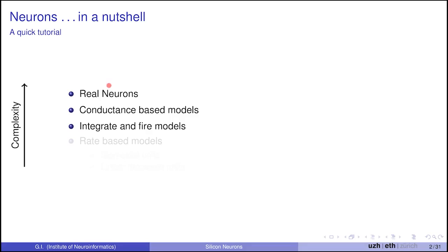Now, why would someone want to reduce the complexity of a neuron if you want to stay close to biology? Well, the thing is, there are limited resources, and complexity requires a lot of CPU in case of software, or a lot of area and memory in case of hardware. So if you have limited resources and you want to create a large network with many neurons, it's just not feasible to put circuits that model in great detail all the single proteic channels of a single neuron. Even though you have real time with silicon, it's just going to take too much area.